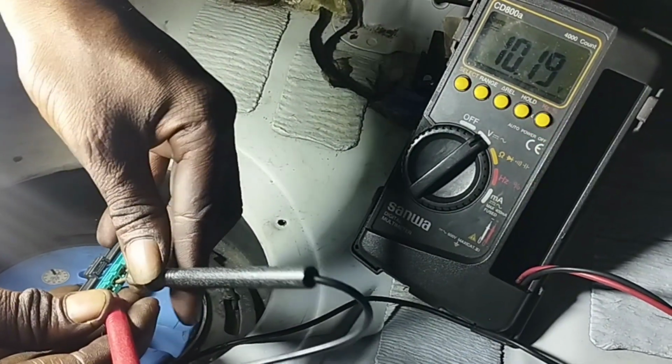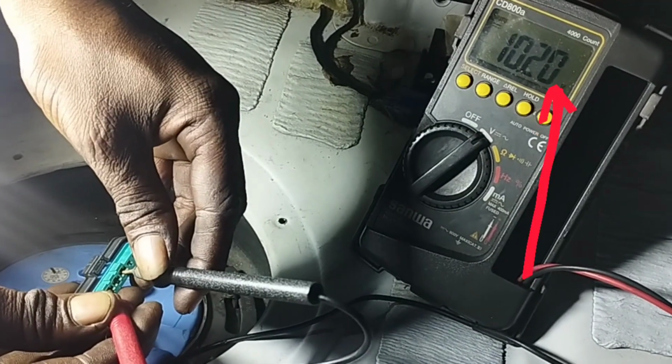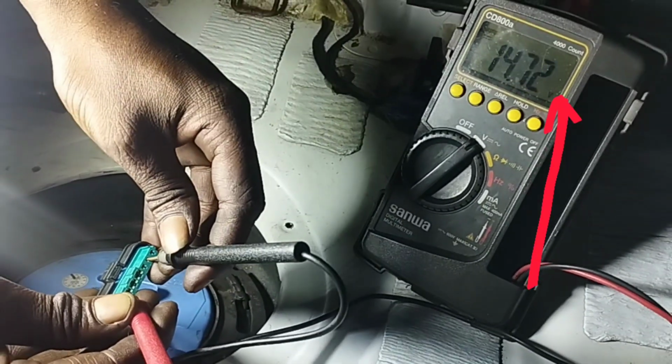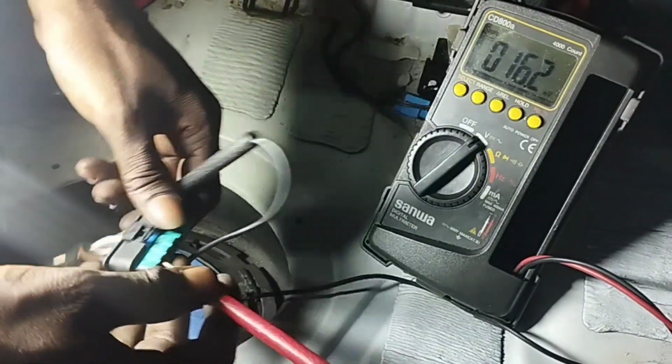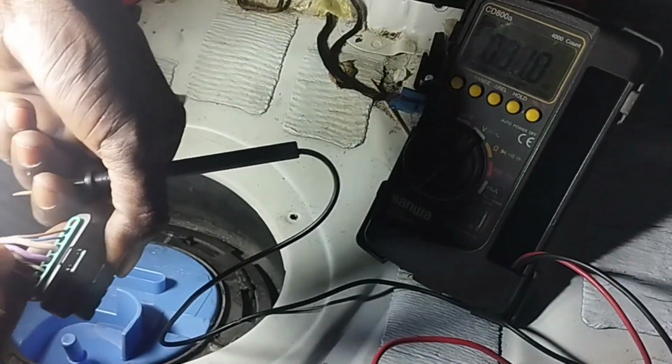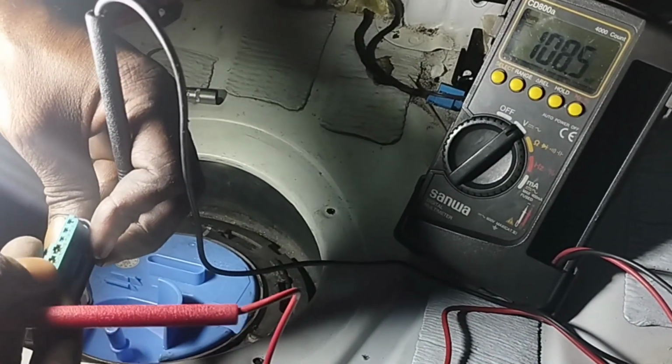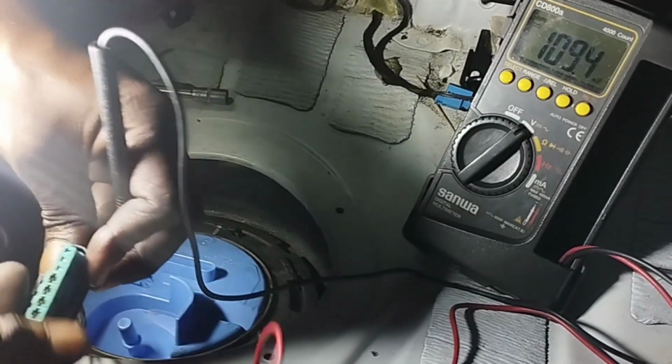Check that the ground signal line of the fuel pump socket number 2, number 3, number 4, number 5 and number 6 wire is OK. All ground signals are above 10 volts. There is no problem with the wiring in the Mercedes-Benz E-Class car fuel pump 6-pin wire socket.